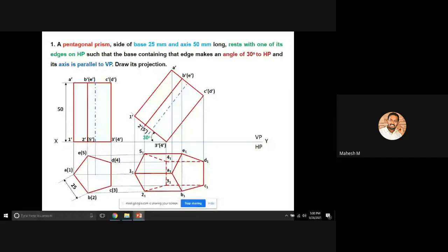So this is the final diagram for this problem. Here the red color lines are the solid lines. Okay, so you have to highlight these with your HB pencil. The remaining lines that I have marked now, like the projection lines, should be marked with a 2H pencil. But all of you have highlighted everything fully. That is why the marks have been reduced.